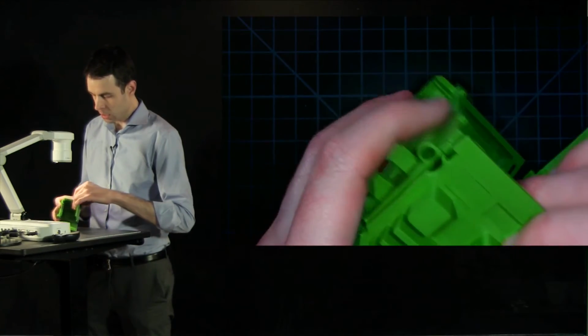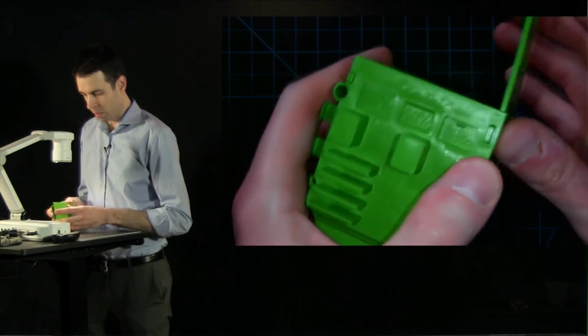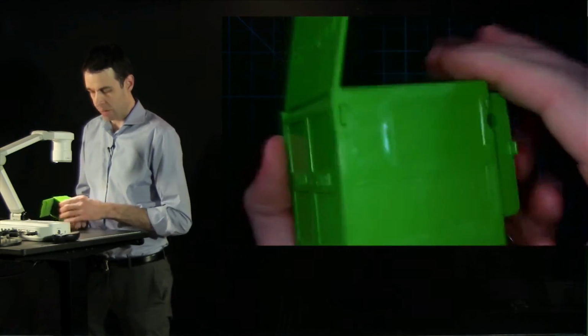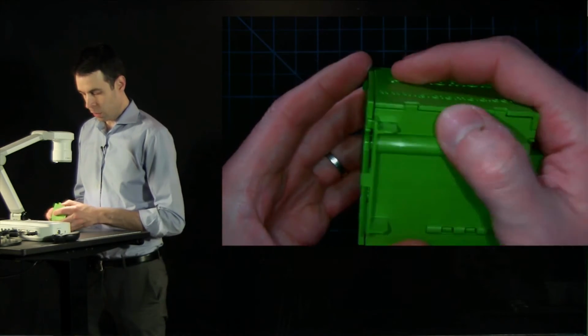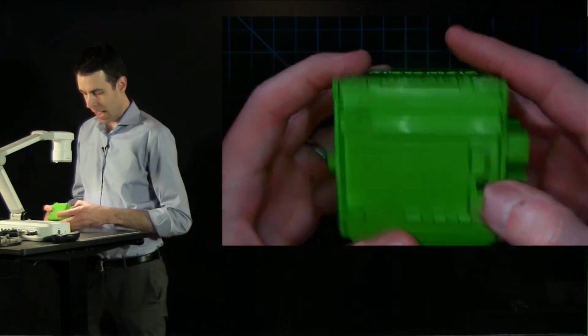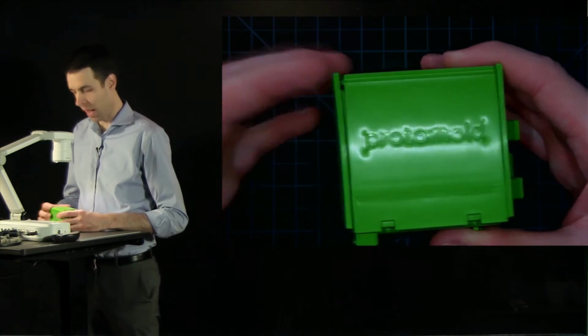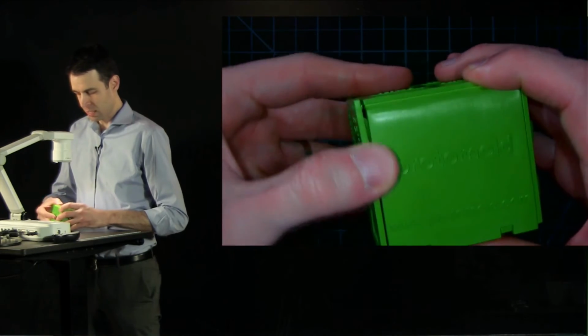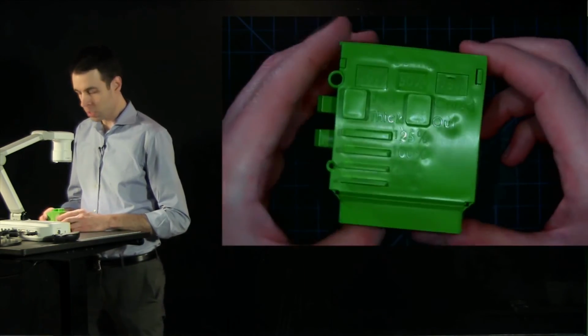And they also build in a lot of snap fits. And design of snap fits is more of an advanced topic, but it's something you can find a lot of information about online. And the tolerances of different injection molded areas can be managed to allow plastic to snap together. And that's one good thing about the compliance of plastic, is it can be designed to have nice snap fits.